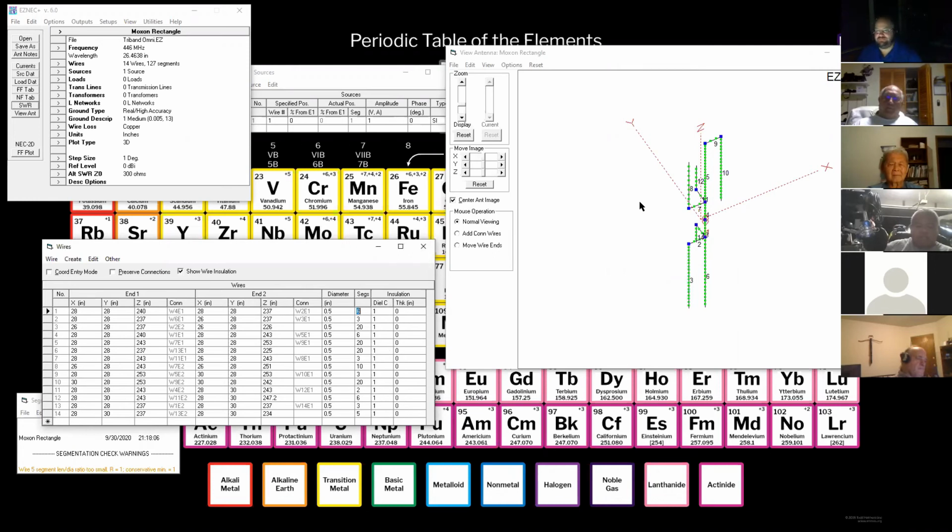And you typically run, like, how many segments would you? When I'm just spitballing an antenna, shooting from the hip, I try to go with about 1 per inch for a VHF antenna.